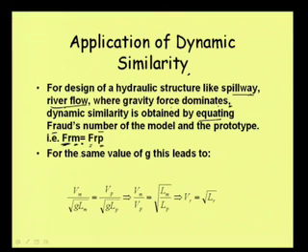When G is considered the same, we can get an interesting relation from Froude number similarity. The Froude number, as we know, is V by root over G D.